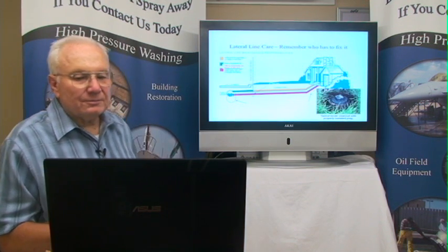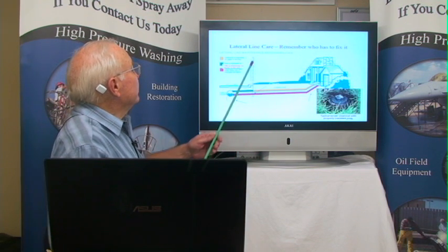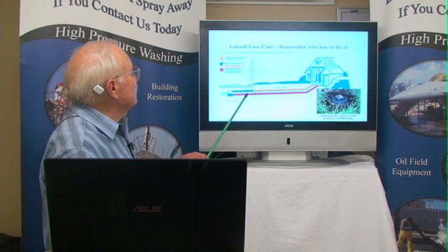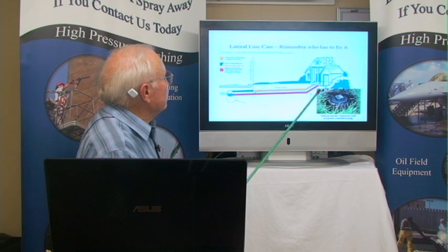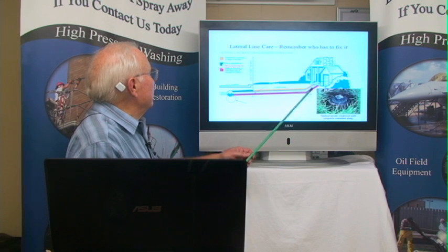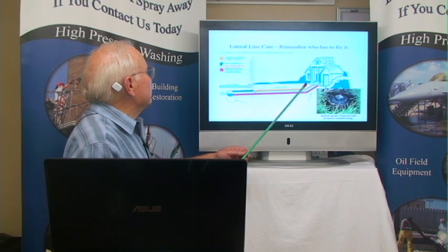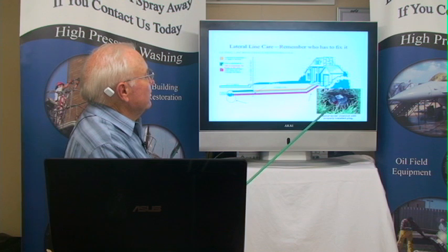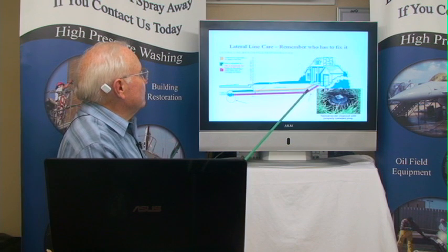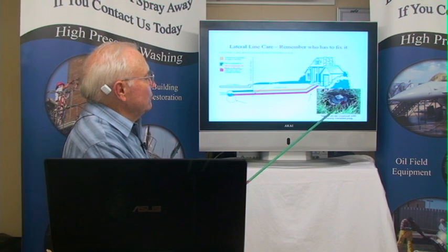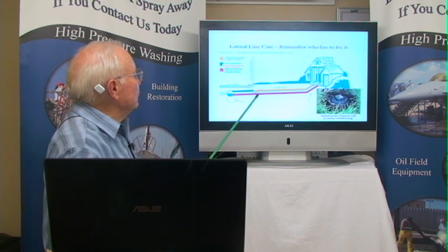Lateral lines. Okay, here's the street right here. On out here is the public sewer system. Here's private property. So your cleanout ports are going to be in this area here. So the cleanout port, and there's an example one, is going to be on the outside of almost those facilities. That's if this line gets clogged up, that you can take that loose and clean out this sewer line.